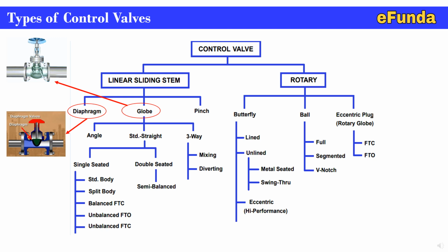Globe valve is also called stop valve or shut off valve. The opening and closing parts of the globe valve can be seen from the animation, where the plug shape is a valve disc, the sealing surface is flat or conical type, and the valve disc moves linearly along the center line of the fluid. In the animation, one can see the operation of the globe valve.